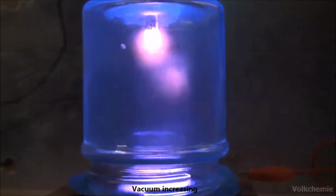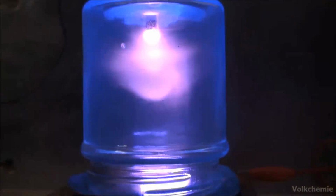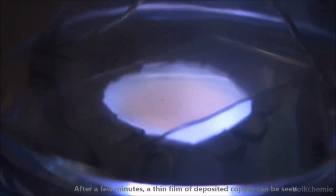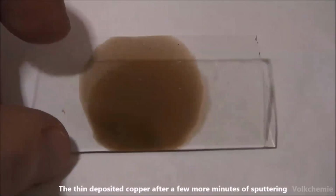Now the vacuum is completely increasing. Look here carefully at what happens during the ion sputtering time. Now gas is passed. The glass is now being covered or sputtered. After a few minutes, the thin film is deposited. Copper can be seen easily. Now the copper has been deposited onto that film. Look here, this is the copper thin film. So copper metal was deposited onto the glass slide. Glass is the substrate, so that type of process was happening.